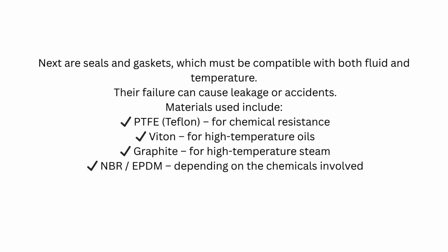Seals and gaskets. Next are seals and gaskets, which must be compatible with both fluid and temperature. Their failure can cause leakage or accidents. Materials used include PTFE, Teflon, for chemical resistance, Viton for high-temperature oils, graphite for high-temperature steam, NBR, Neoprene, or EPDM, depending on the chemicals involved.